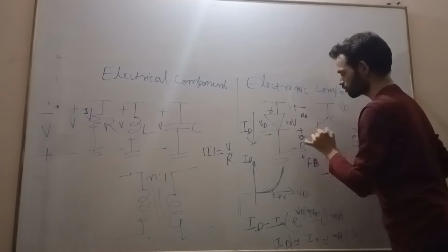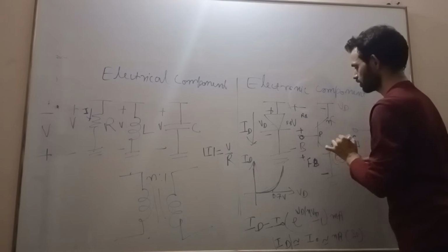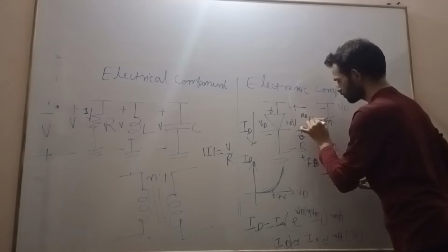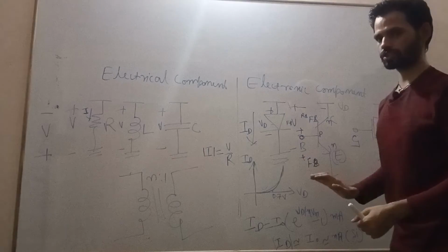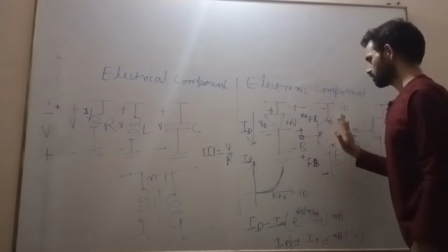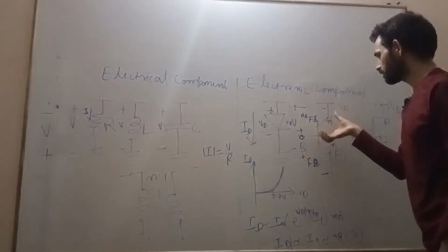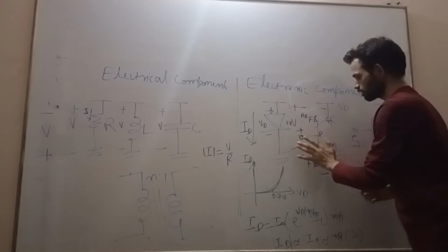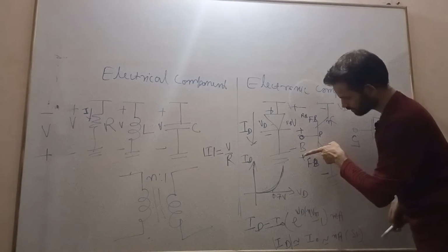And if I make it positive and negative, this is n type, this is p type, this is n type, so it also becomes forward bias. So both are in forward bias, which means it is in saturation mode. So therefore it acts like what? Switch on.